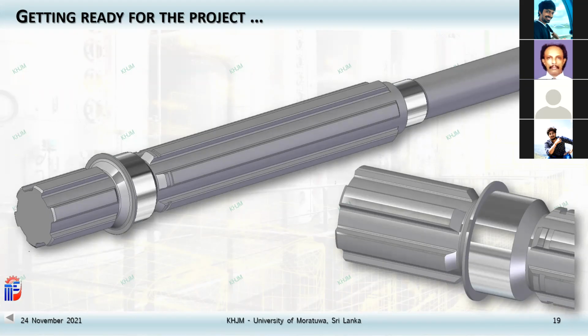And I've seen many students. So for example, here you have the spline shaft, the bearing diameter. Like you can see, I can take the bearing from the left hand side because it is bigger. The step is to stop the bearing. Otherwise, when you assemble, there's no reference. Someone who is assembling should know exactly, push the bearing to a corner and then it hits on something. Okay, that is the point that I want to stop. Right? You should have all these things.